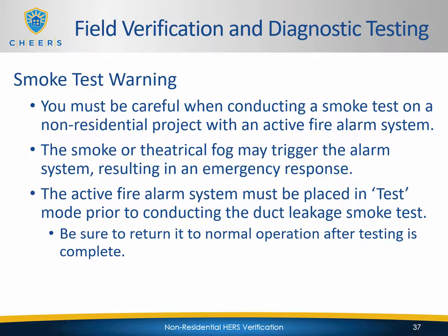So get with the job site superintendent, make sure that they know that you need to do this smoke test and that it may affect the smoke alarm. Get them to put it into test mode, do your smoke test, and then make sure that they return it to normal operation after you're complete. But yeah, save yourself a lot of hassle. Get that thing into test mode before you do any kind of smoke testing.